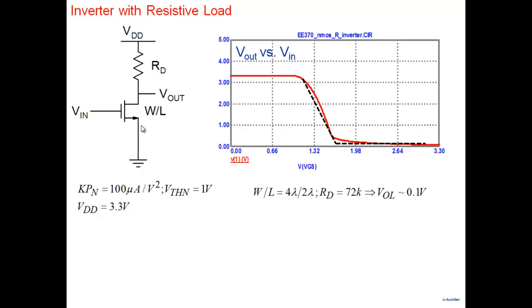And in the saturation region, gain is usually large. So what happens is, you go from gain equal to 0, and you start going to higher gain very rapidly because the transistor is in saturation region, right? So one very simple approximation could be VIL is simply equal to threshold voltage. I don't even find the -1 point in this case. I'm not saying for every case. In this case, VIL is very close to the threshold voltage.